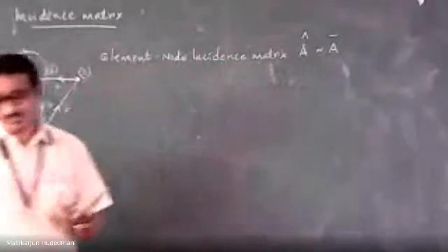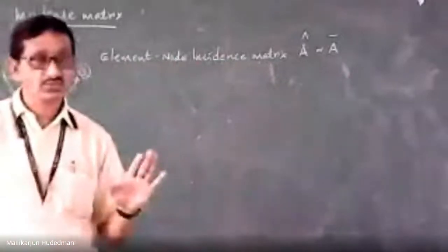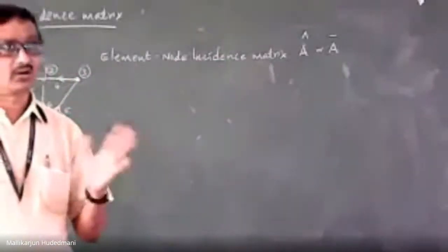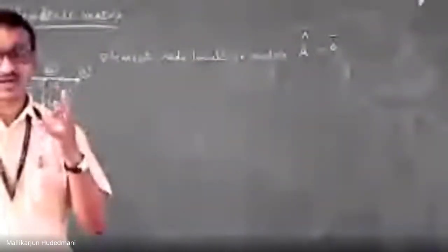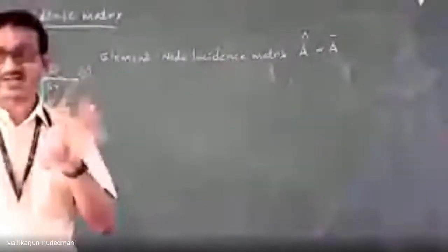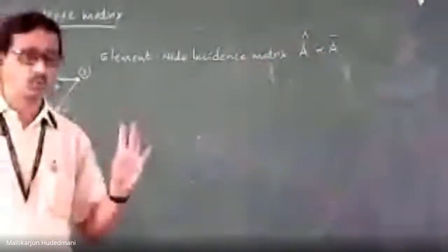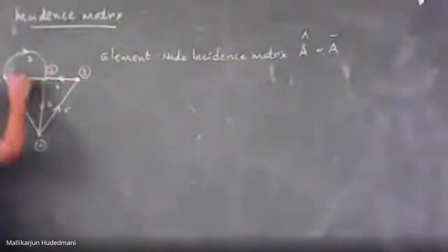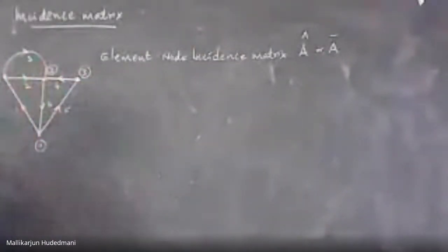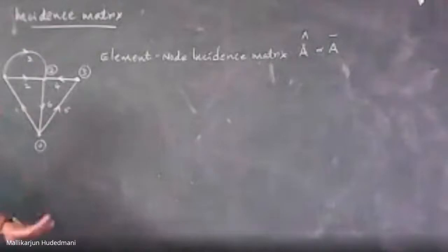It should be a representation of all the buses and all the elements, how they got interconnected to one another. That relationship I am going to confine into a matrix by a simple rule. So I have an example. I have a 4 bus system. There are 6 elements in the system, and all the 6 elements are oriented by direction. You may ask me, how would you give this direction? Arbitrary. If it is given, I will use it. If not given, I will make my own arbitrary direction.